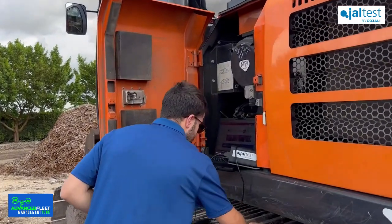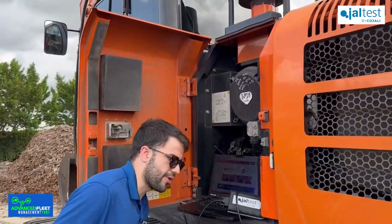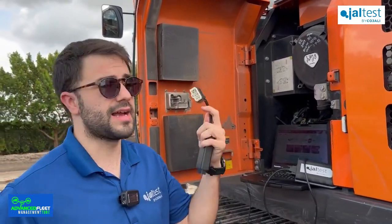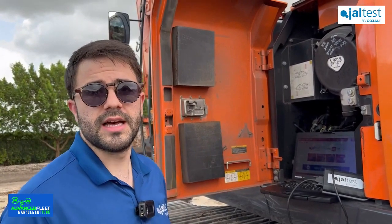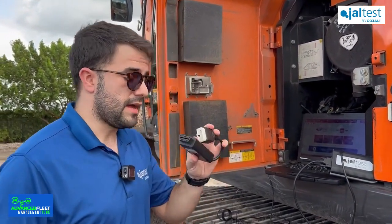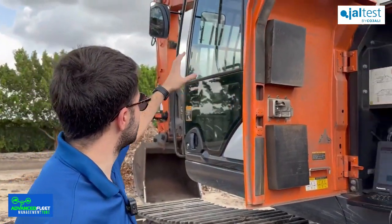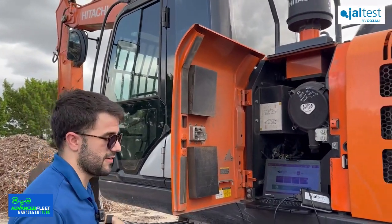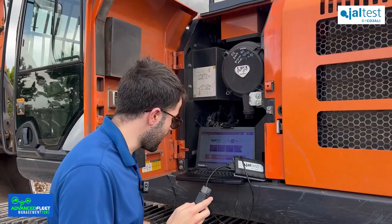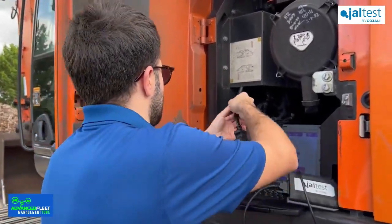All right, so for this Hitachi excavator, we have two connectors that we are gonna use. This very known connector is for the Hitachi hydraulics, cabin modules and body controls, that is very common also in John Deere excavators. And this port is gonna be placed on the cabin, okay? And it's gonna allow us to communicate with the hydraulics and all the Hitachi stuff. But when it comes to do the maintenance and the diagnostics on the Isuzu engines, we are gonna need this new connector. So I'm gonna place it right now. I'm gonna show you how it works.